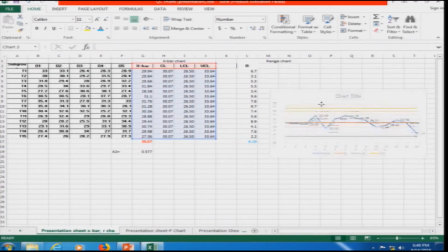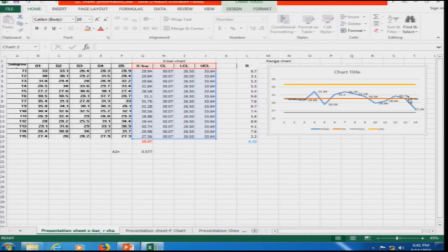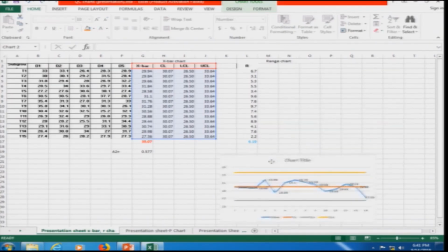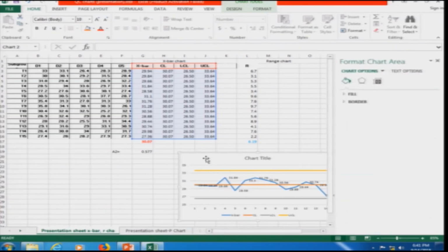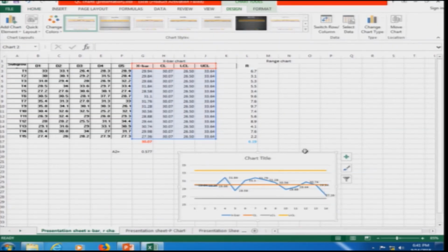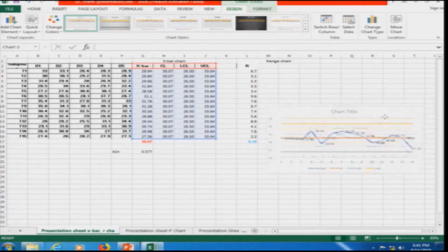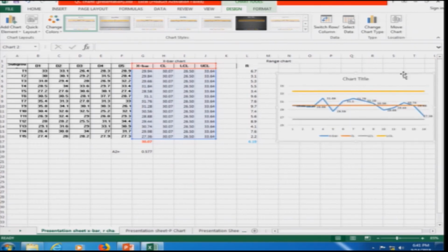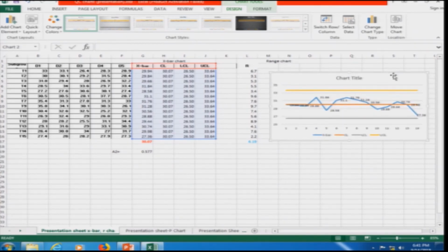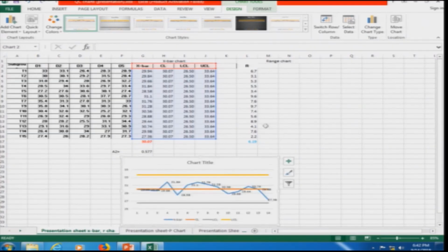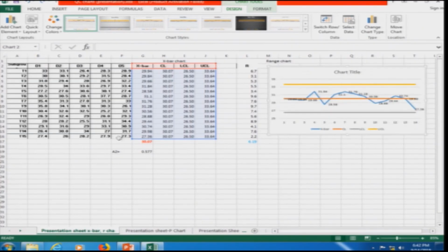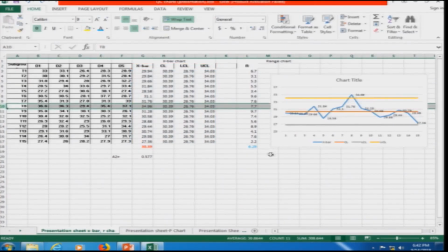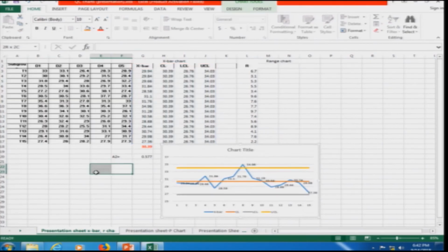Now the process, if you can see, is within the limits. So, here we can say that this is not a very serious issue. We need not worry, just by elimination of that one value. There is some error that has happened, just because the machine might not have worked properly, or some temperature was not taken properly, the reading was not taken by the observer properly or not noted properly, some error might have occurred. So, the overall process is within control. Okay. I will just undo this so as to keep all the values, this T8 as well. This is my X bar chart.